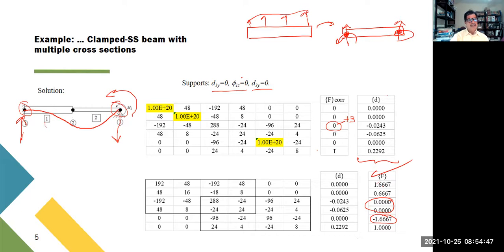What we're going to do is calculate statically equivalent external forces, and we're going to use an energy approach. Basically, it's something like this. It's the integration of p of x times the vector of the shape functions, dx.